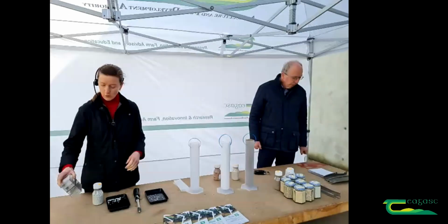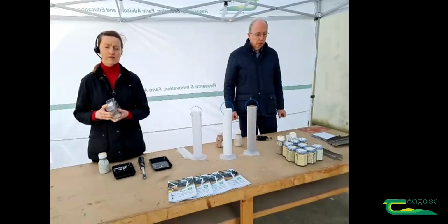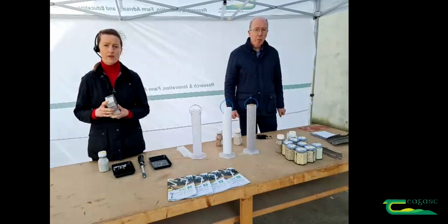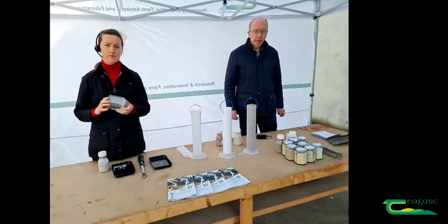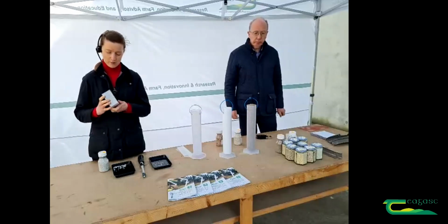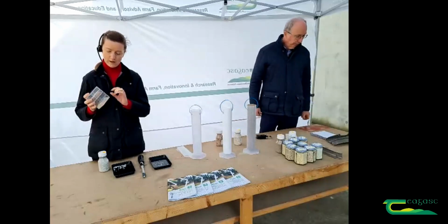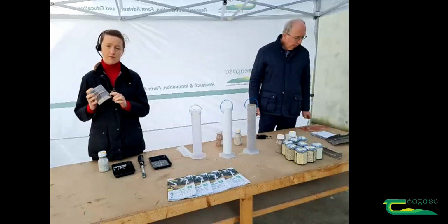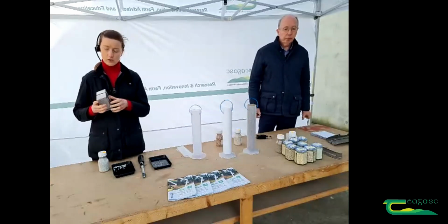When we look at the size of the fertilizer, generally what we're looking for is that 80% of the granules fall between 2 and 4 millimeters. The reason is that you get a nice even spread out in the field when you have 80% between 2 and 4 millimeters. So this is a sieve test here. I have the fertilizer sample in the 4.5 plus mil compartment, and what we're looking for is that 80% goes between 2 and 4 when I shake it through.